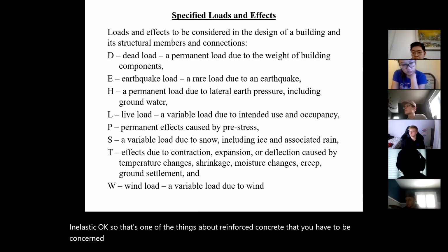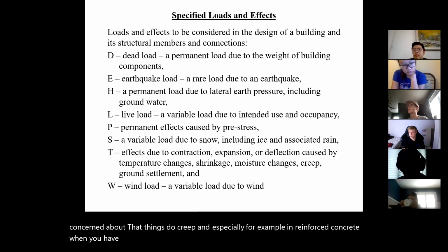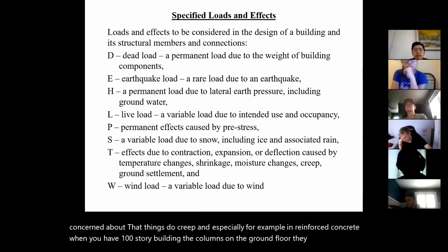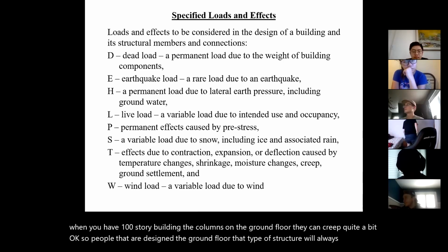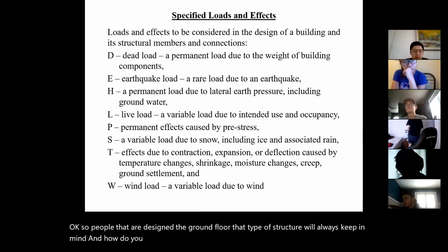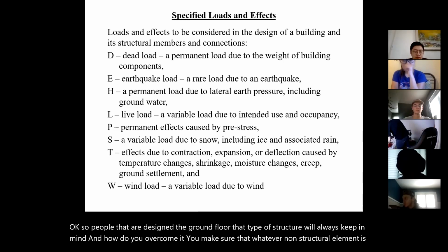Things do creep, and especially, for example, in reinforced concrete, when you have a hundred-story building, the columns on the ground floor can creep quite a bit. Okay, so people that are designing that type of structure will always keep that in mind. And how do you overcome it? You make sure that whatever non-structural element is going to be below it, you leave a gap.